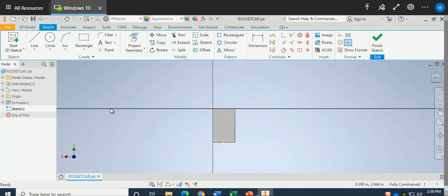If you divide 1 inch by a half inch, that is 8/16 of an inch, and 8 plus 5 is 13/16 of an inch. So we're going to draw a 13/16 of an inch line from the top left to designate the center point. When you start at the top left corner, you type 13/16, enter, and now you can draw the line. What is the length of the line supposed to be?